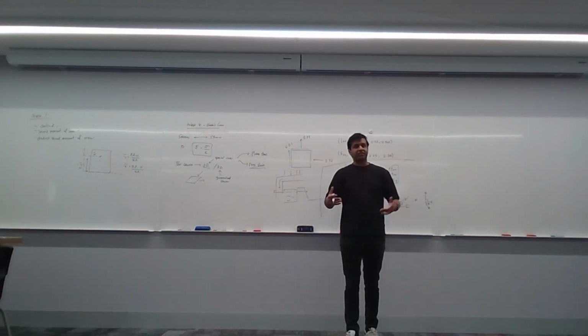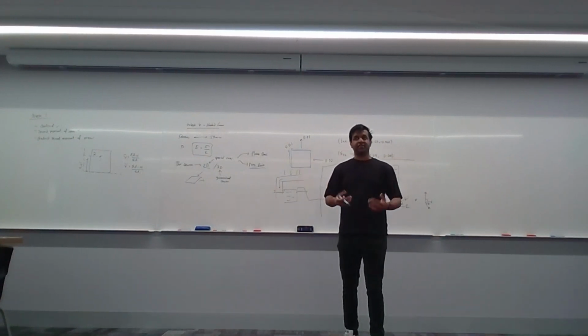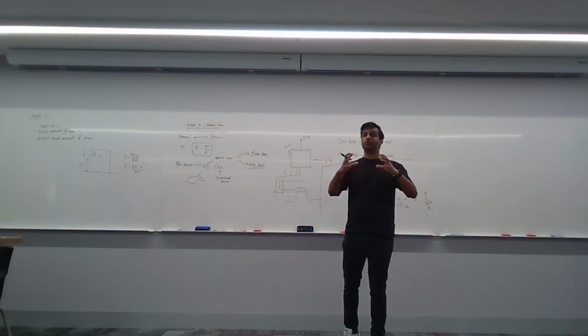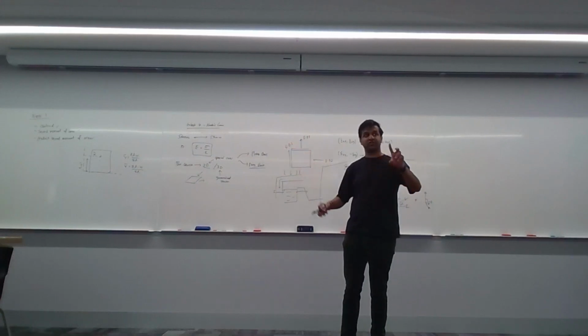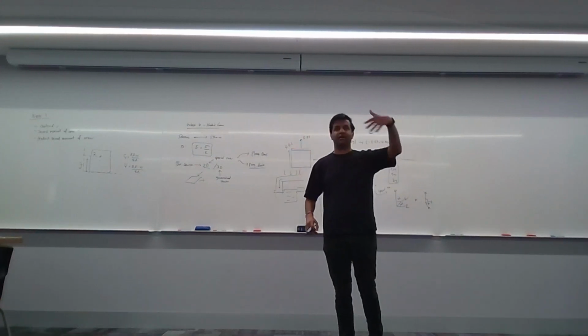Of course, for every situation, have a think about it. Ask yourself, does it make sense? Remember, plane strain is strain only in two directions. Stresses can be everywhere, it doesn't matter, but strain only in two directions. That is plane strain. Plane stress is stress only in two directions. Strain can be in however many.